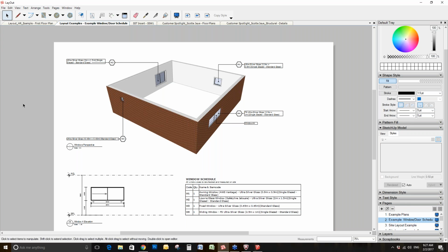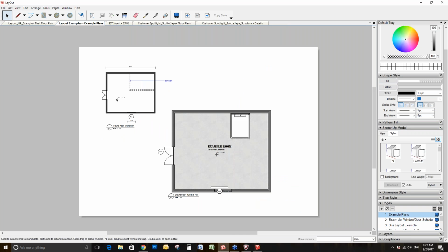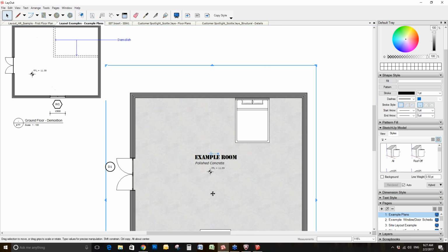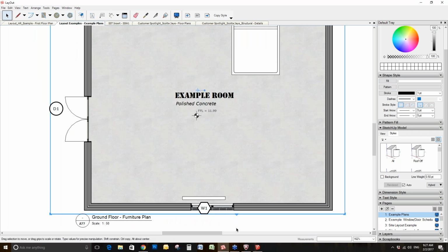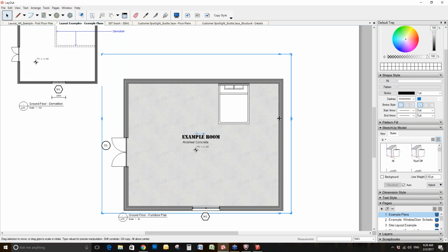So styles, and understanding the style is really important. However, if you go back into the plan actually, you can further manipulate your line weight. And again, this is one of the big things that people don't really understand. They do think that once you have brought in the model that you can't really manipulate the overall line weights here either, but you can. When you click on the model reference, you're able to go into the SketchUp model, go into the styles, and in the styles you're able to see this line weight, and this represents overall line weight.